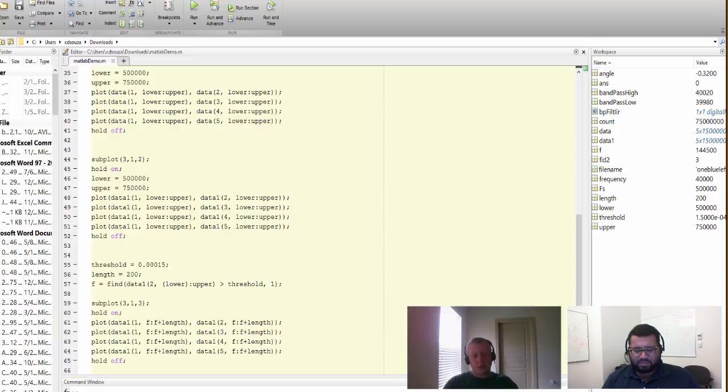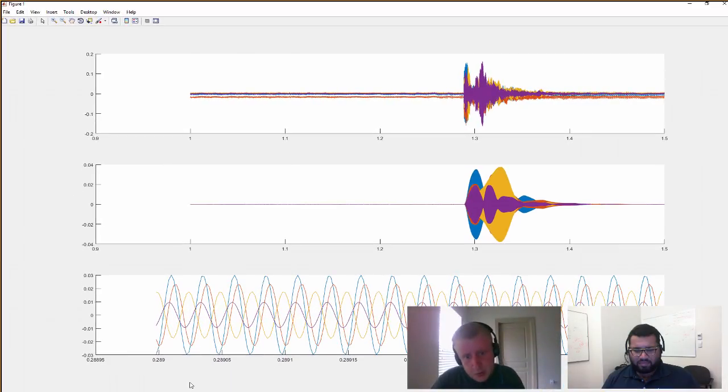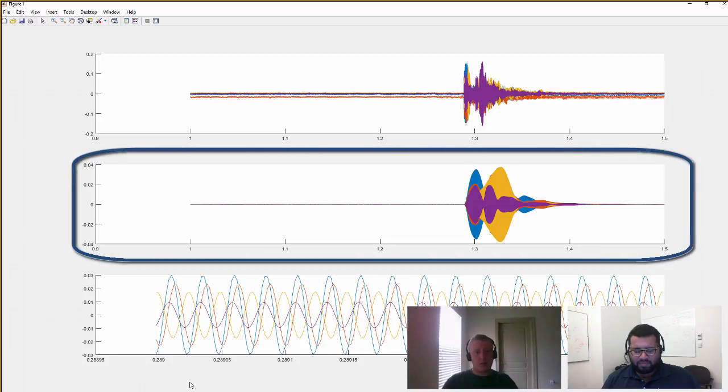And what we're doing to find this data is we're just using right now a simple thresholding technique, looking as you move across the data. In the plot above you see you have really zero noise leading up until that front of the waveform. So what you can do is just simply look for that starting increase in slope above a certain value, and you can determine you've hit your front of the waveform there.